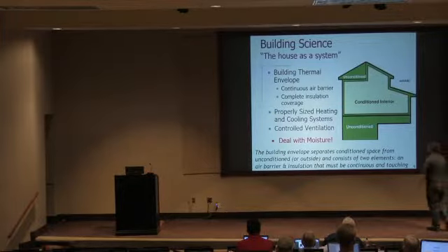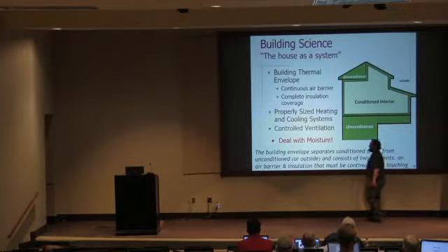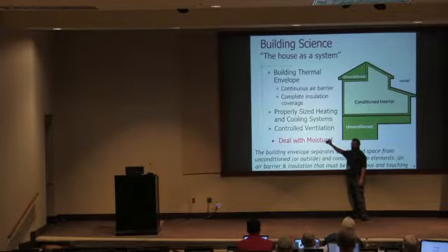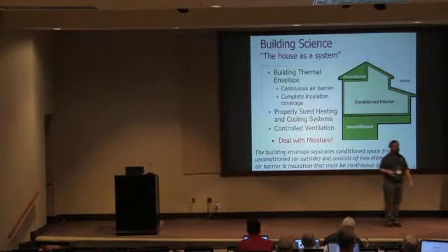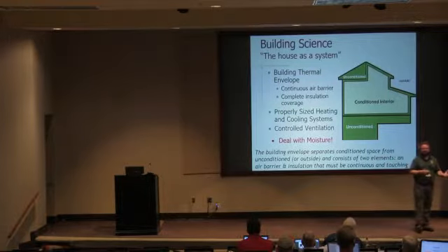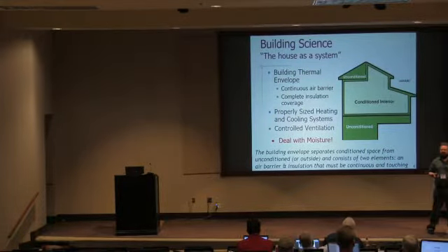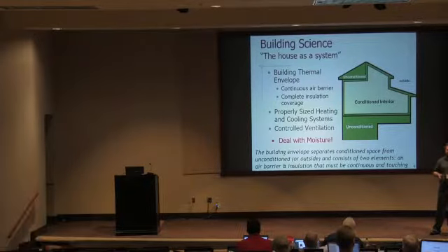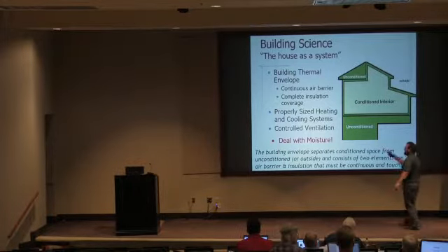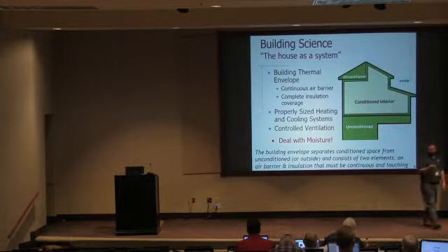So we've got to deal with moisture load in our homes here, and tightening up the house can actually help. People worry that when you tighten up the house, you're going to create mold issues. You could, if you tighten up the house and you don't reintroduce fresh air ventilation. That would be a bad thing. But if you tighten up the house correctly, you size the equipment correctly, and you properly introduce fresh air ventilation, then you're set up for success in managing potential moisture problems in the house.